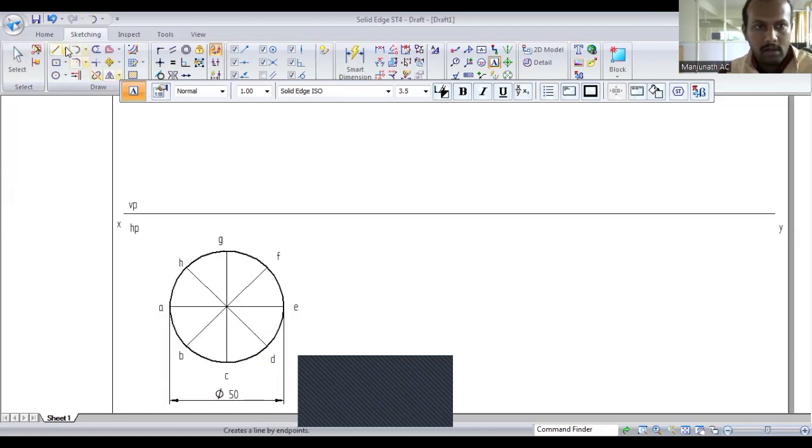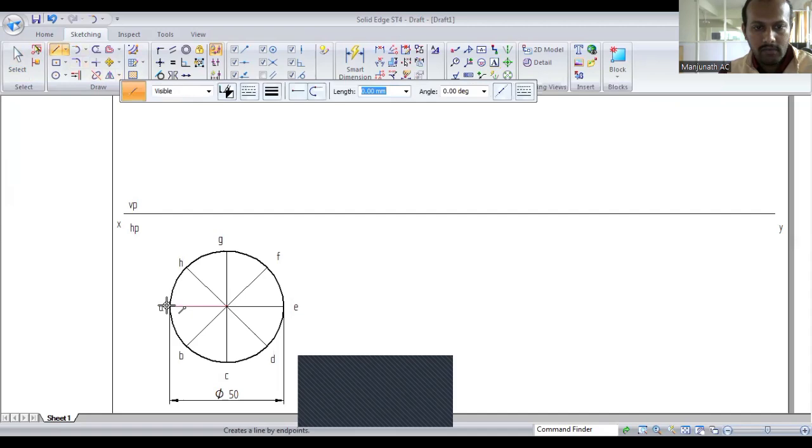Okay. So after this, projection to the front view. Use the projection lines, make it 0.13. So A is over, B and H, C and G. Okay, so D and F, and finally E. Use the line command again, change the width. So split this one for the front view like this. You'll get the endpoints easily for projection.